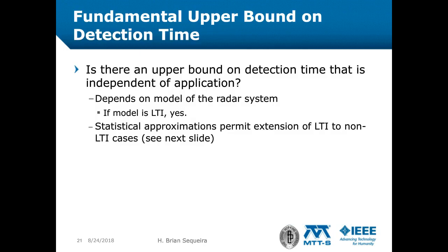Further to our discussion on lower bound on detection time, the question arises as to whether there is a fundamental upper bound on integration time. The answer to that question depends upon how the radar is modeled. If the radar is modeled as a linear time invariant system, LTI, then as we have seen, fluctuations in target scatter and weather negate LTI assumptions.